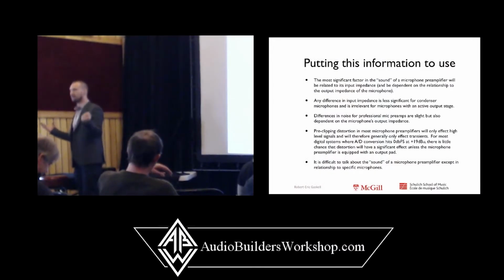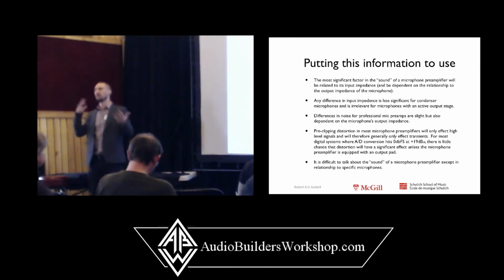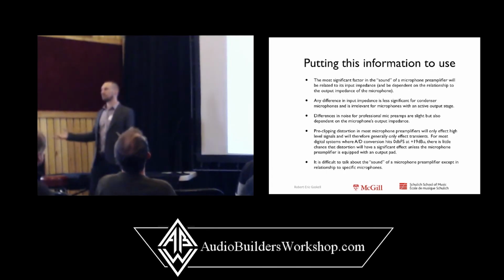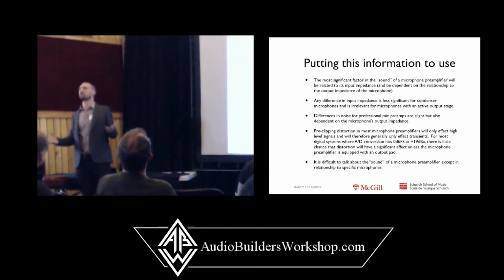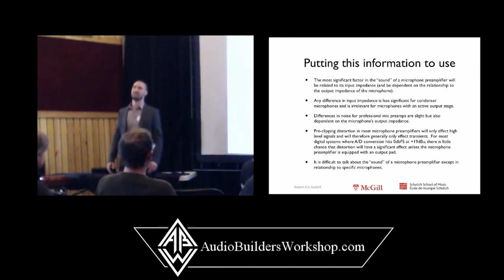Anyways, all this information hopefully will help you make more creative decisions when you've got a mic pre and you got a mic and you need to plug it in somewhere. Thinking about the input impedance, thinking about the distortion characteristic, thinking about where you're going to be running it in the gain range of the mic pre, all can contribute to what choices you're going to make in the studio.